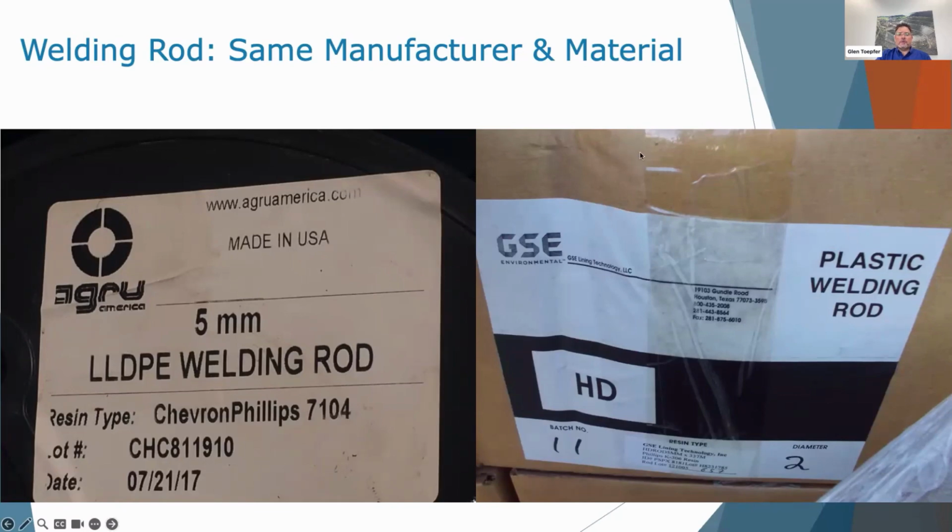But I think the graphics I showed you earlier illustrate differently. My belief is that if you're using GSE material, the Solmax GSE brand material, you should be using the same welding rod that came from that batch that was used to make that material, or at least the same manufacturer, because their proprietary formulations may be different. If you're using Agru HD rod, maybe it doesn't have the same melting point as the GSE, and that can be problematic. It's going to cause issues with quality welds and long-term performance, which may be unknown.